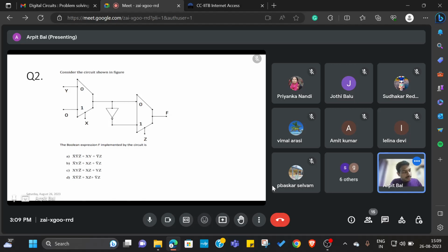Okay, so let me mention one thing here. Let's say you have a mux. 0 and 1 are the inputs, and let's say the select line is S, and 0 takes input A and 1 takes input B. And you have the output named out. So the equation for this mux will be out is equal to S bar A plus S B. So try to remember this, because this will be helpful in constructing bigger and bigger expressions, right?